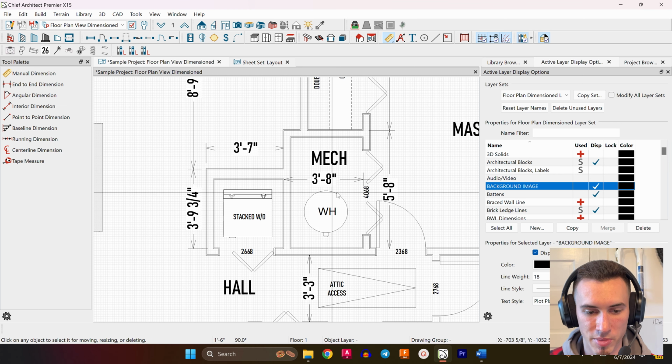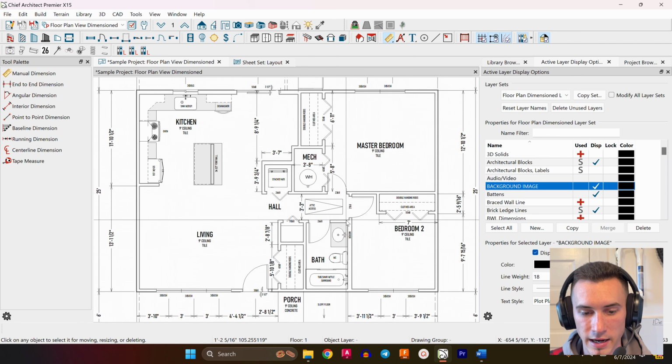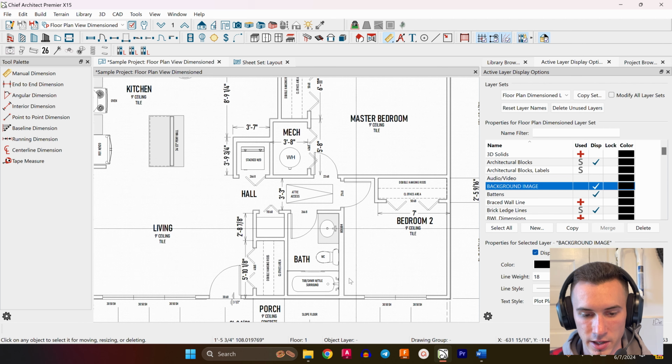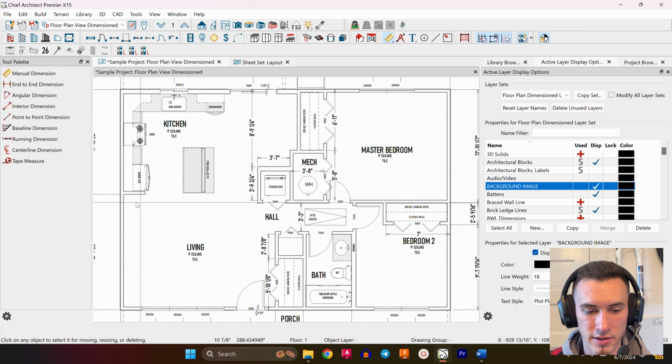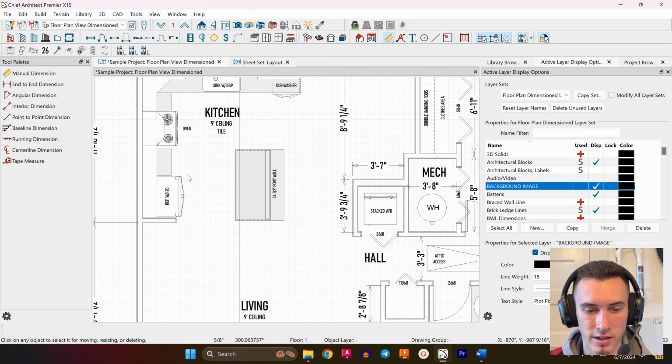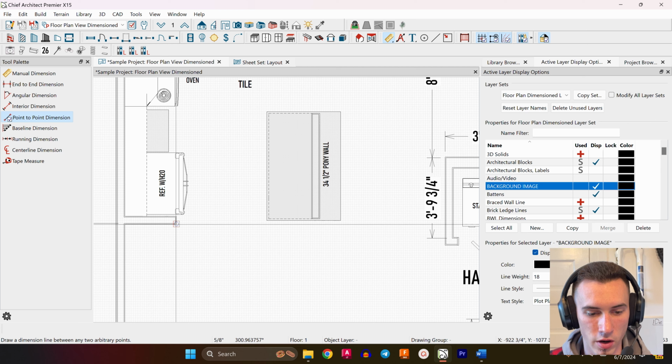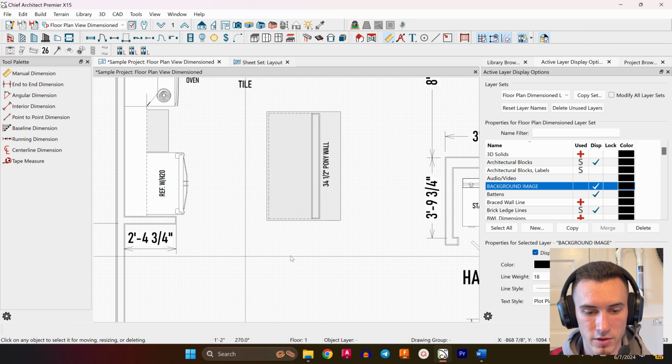That's a legible spot. Now all of these walls are actually defined, and the doors are defined because they're centered, and this one's on the edge of the wall. It doesn't need a dimension. These doors are dimensioned from the outside. The only thing that needs a dimension now is this kitchen space. We need to know how deep this wall goes into the house, so let's throw a dimension on that. That's good enough for them to work with.